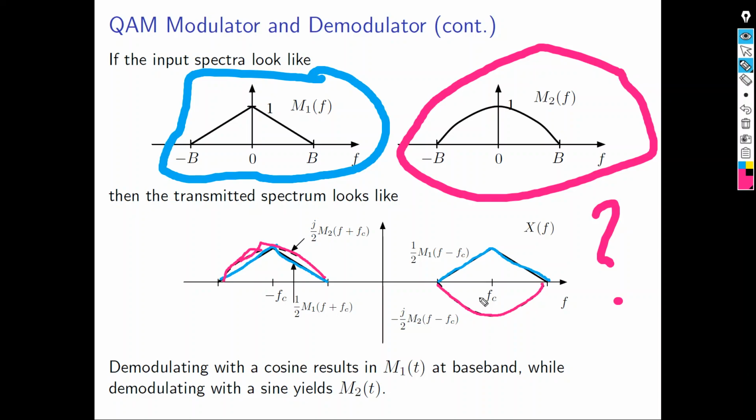Can you see and notice with me that the two signals are using the same frequency? And if you draw them in time, they also use the same time. They are on top of each other. So as you can see, they are superimposed on each other in time and frequency. But you can separate them nicely. Why? Because they are orthogonal. Mathematically, when you make the dot product operation, they get separated.